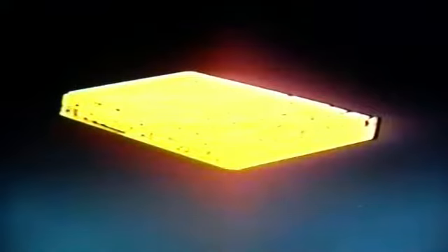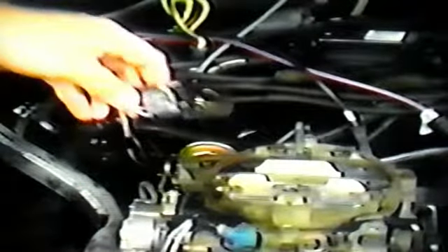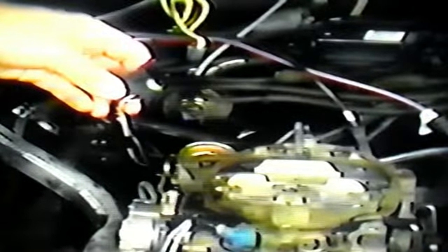However, it's precisely because the ECM controls the ignition coil that you must remember to take control away from the ECM when you start out to set base timing. This can be accomplished on most carbureted vehicles by simply finding the 4-wire connector. It should be coming right out of the distributor, and unplugging it. That will get you back to the basic 4-pin module function where the pickup coil controls the switching transistor.